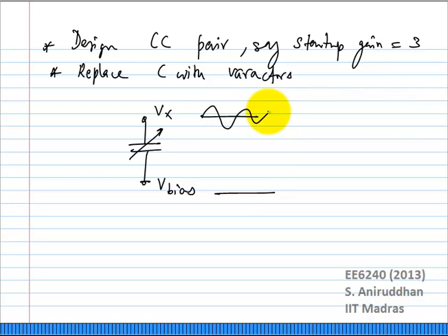The capacitance will also change at the same rate as this small signal. So what will happen to the frequency of the VCO? The VCO frequency will also get the same signal through a nonlinear process. Again, you have to go back to your narrowband FM approximation, the expression that we looked at before, going from a particular amplitude to phase, right? Going from a particular amplitude or phase to the sideband. In other words, the capacitor, the varactor, actually performs AM to PM conversion.